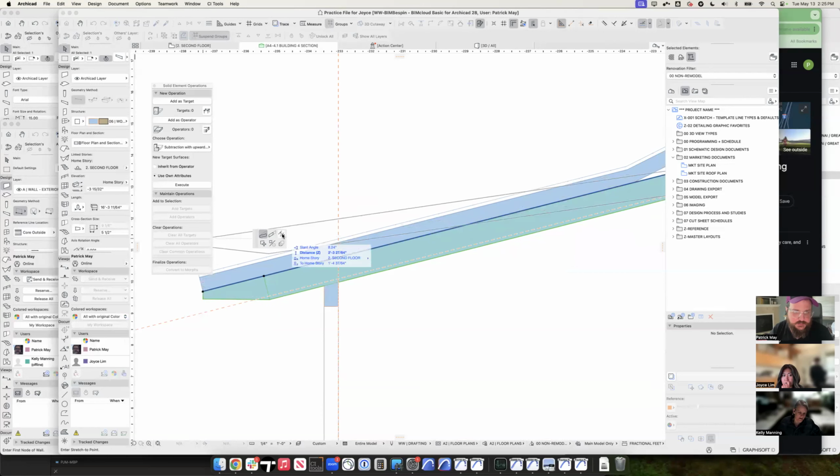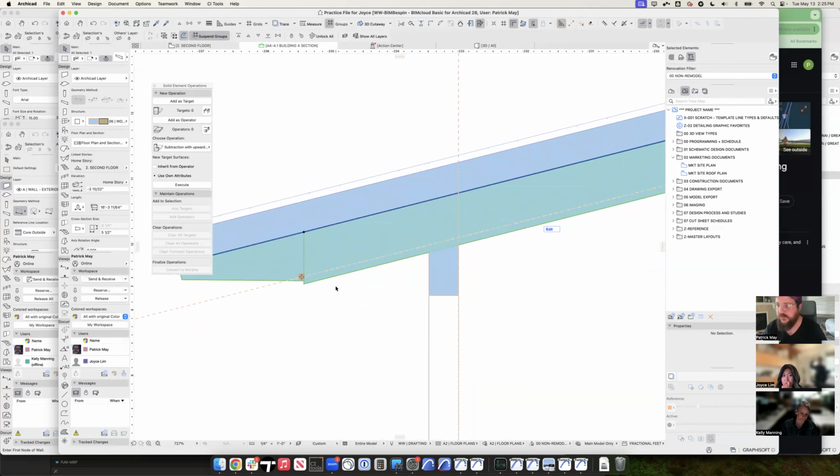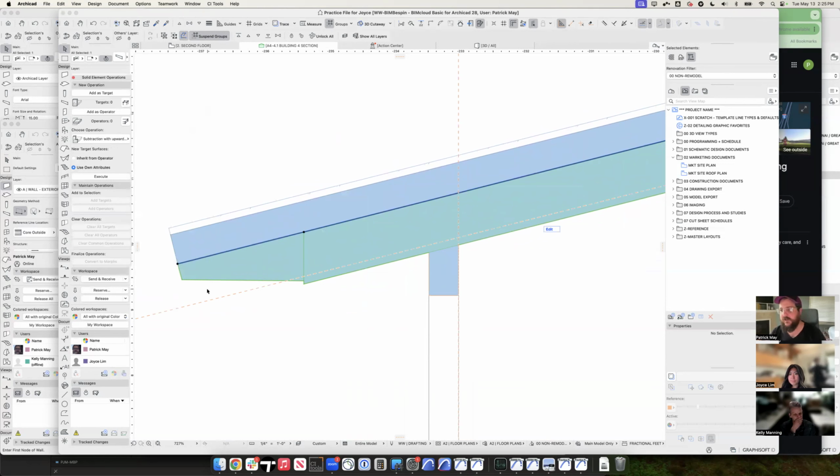You can also adjust the end angle directly in 3D as well, so you can start to modify some of these segments depending on exactly what the design needs to be. You can even get some notches and stuff. So you don't have to have really complicated modeling techniques to model really cool rafter tails. It really depends on what the design is. Obviously, if it's some sort of ornate scalloped profile, there's other things we'd have to do with that. And we can talk about that if and when that ever happens. But generally speaking, unless it's a historic preservation project, we're not doing a lot of elaborate ornate trim work. So this should get us like 90% of what we need.